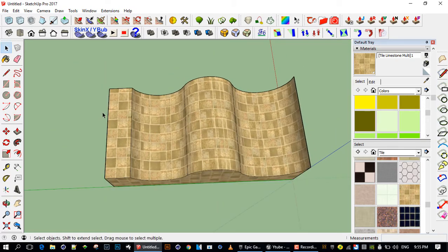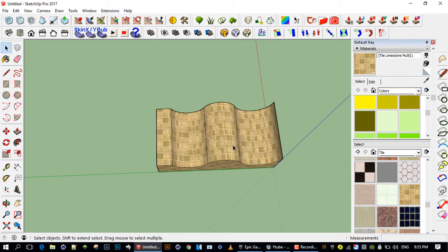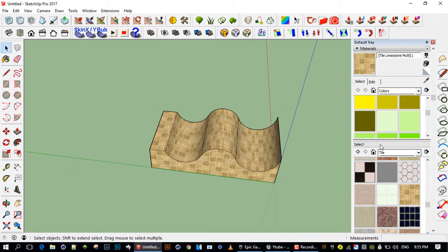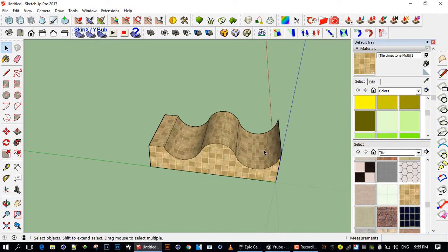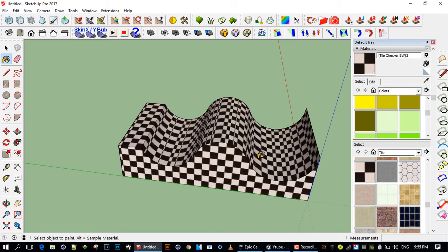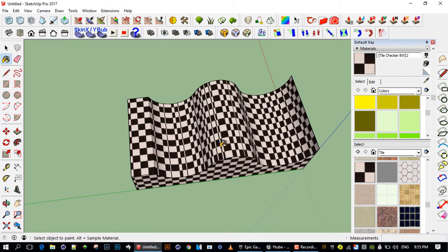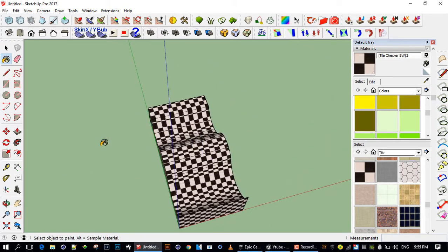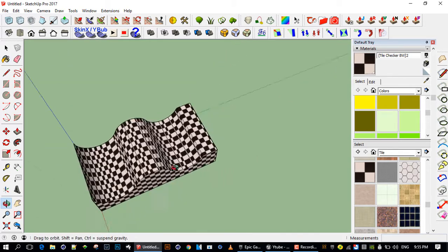The other way to project on the top here would be to draw a surface, place the texture on, and before you use your eyedropper tool, on the texture you right click and say project onto that flat texture. You take your eyedropper tool, you make a sample, and then you paint on the surface and it will come out a bit better. However, it still won't come out as expected. There still will be distortions. Trust me on that. I've done it, and I don't want to repeat it in this exercise now.